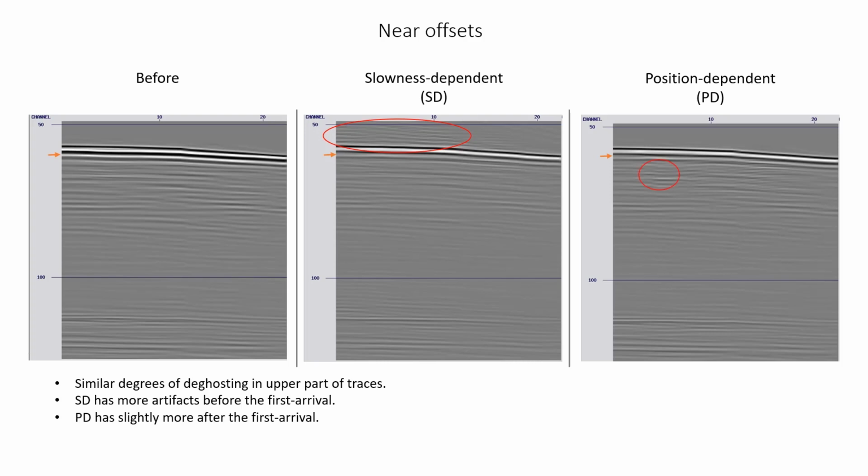And you also notice that there's a little bit of ringing after these, though, in these traces here, the very slight ringing artifact, and that's because the delay is quite large in those positions, and where the notch has moved into the largest amplitude in the input signal, so it makes more of a profound effect.